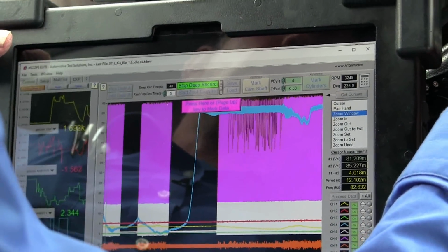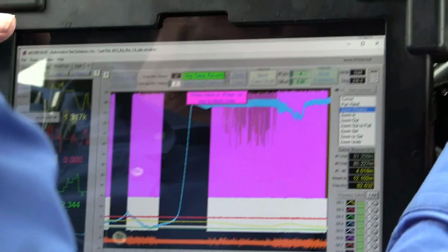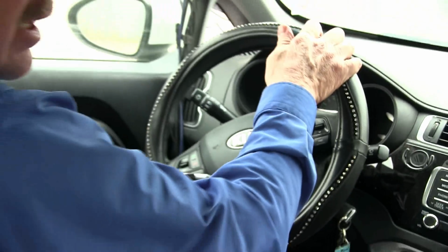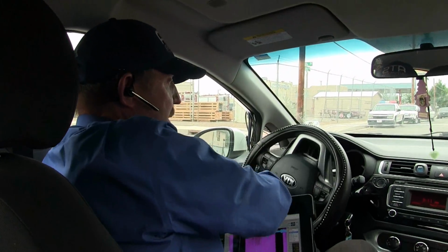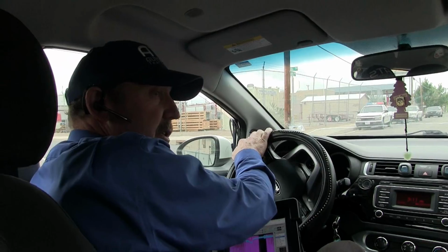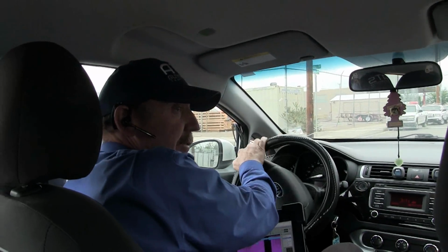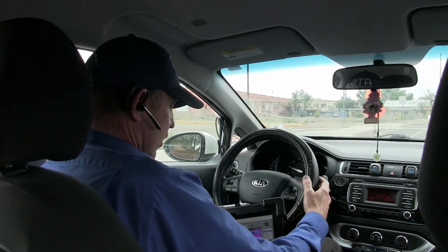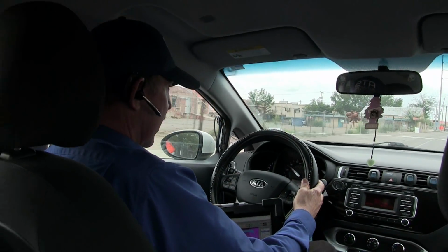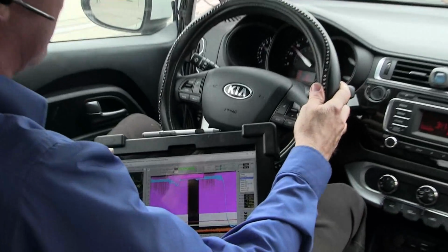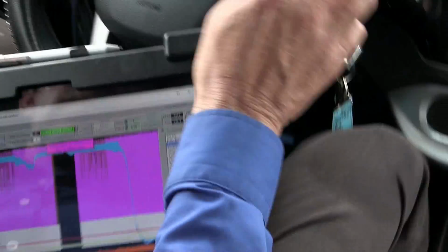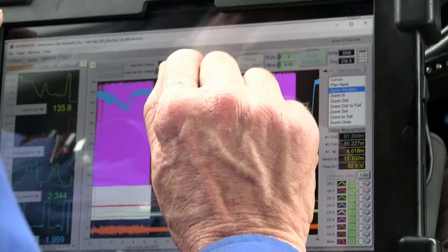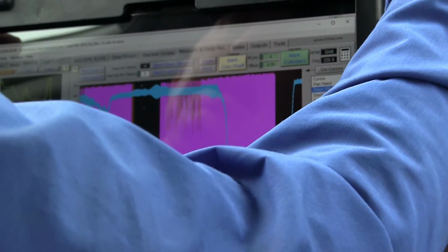Yeah, so it's got a low pressure feed problem, there's no question. So we'll need to figure out what's going on with that feed, but first let's just get it to fail. We can see that the low pressure is failing for sure. Come out here where we can get in it a little bit longer. So it pulls up. We lost our pressure there. Right there, it just flat cut out. So I'm going to get back out of it. As soon as I started to pull my foot out of it, I could feel it pick up. So we're going to stop that data.